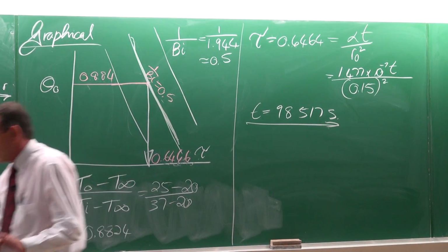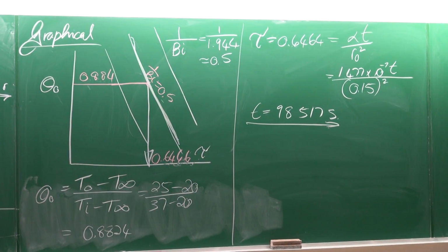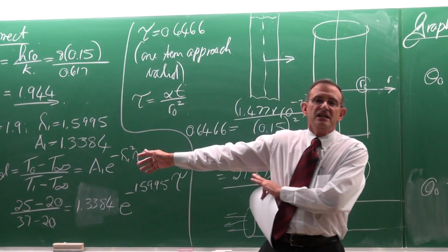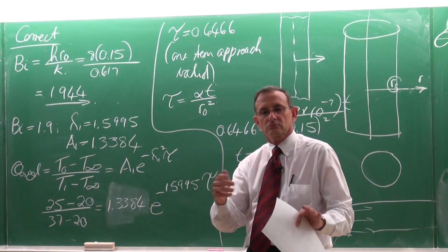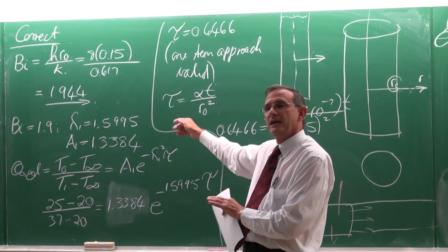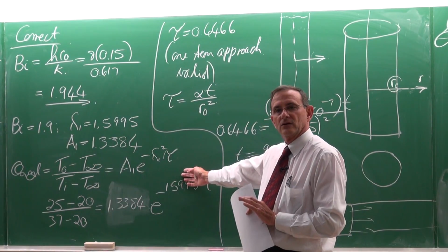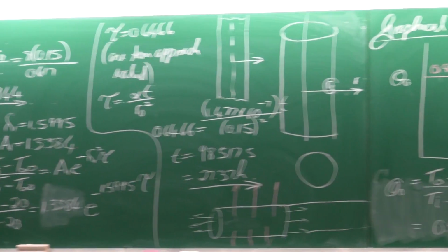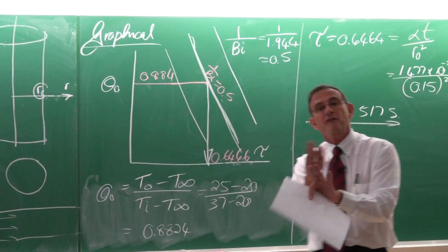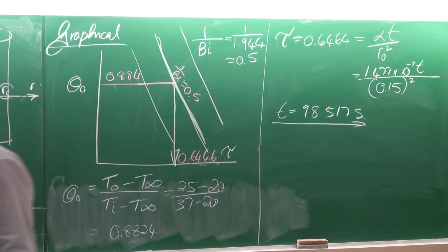What I like about the Heisler charts is that it is so easy to make a reading error from the tables or to make a finger error when you do a calc. So it only takes 1 minute to check the chart and see if your order of magnitude of calculation is approximately right. So that can guide you so that you know, oh, I've made a mistake somewhere.